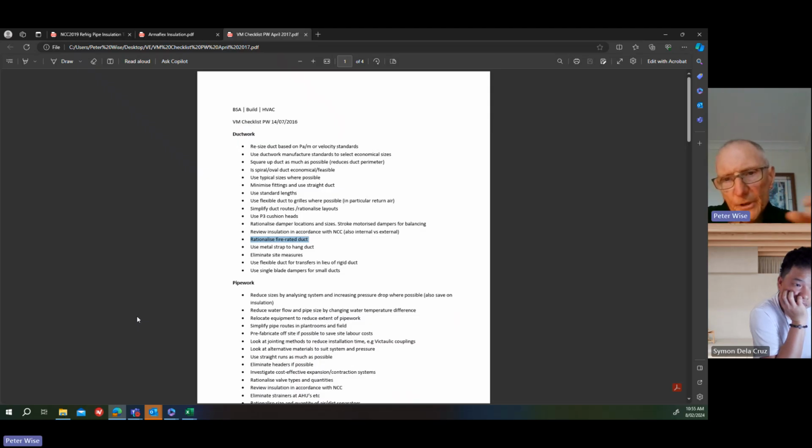And on the exhaust side, because you're going out of the pump room, relieving the air and going through other fire compartments, that has to be fire rated as well. And again, you can't use fire dampers, because fire dampers will close if there's a fire or heat. You don't want that to happen. So basically, your fire rated duct is taking the place of fire dampers.